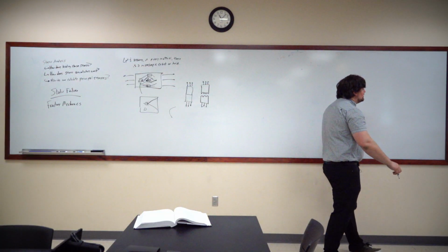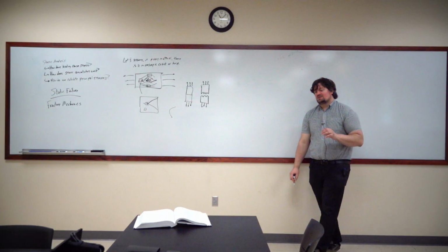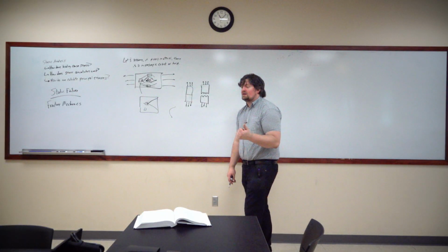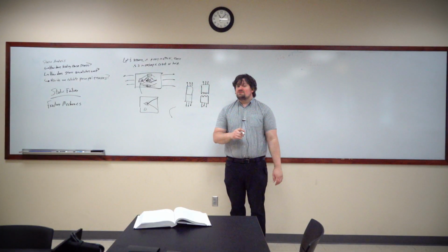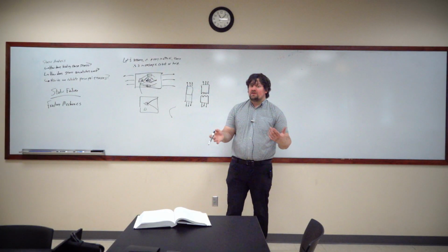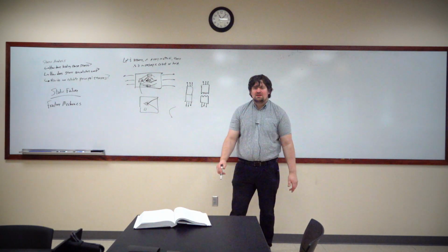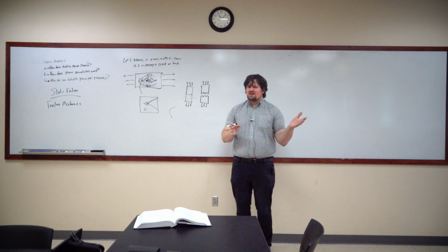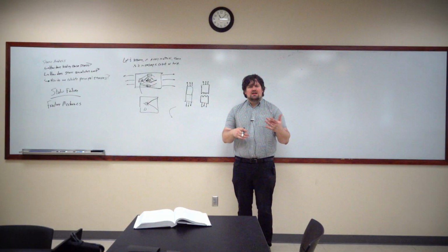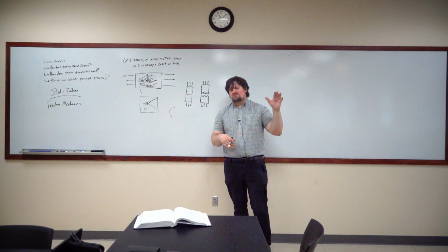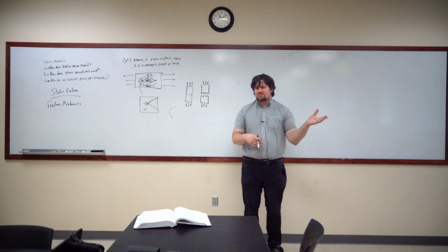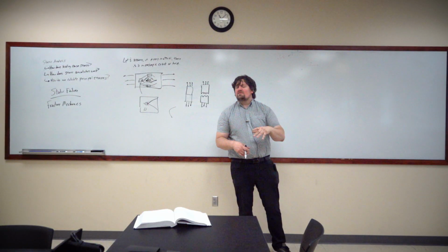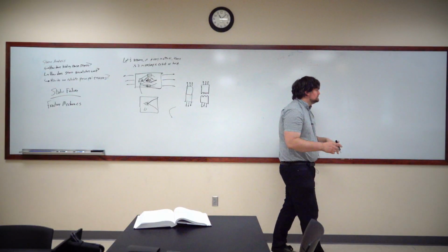On this side of the board, I'm going to break this up into two pieces. Some materials we are finding do not plastically deform. Those materials fail, and it's called a brittle failure. Okay, so our biggest classification and differentiator in failure, static failure, is going to be, we're going to have two categories. We're going to have ductile failure, which involves plastic deformation, and then we're going to have brittle failure, which involves fracture.